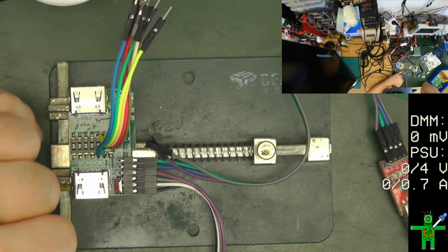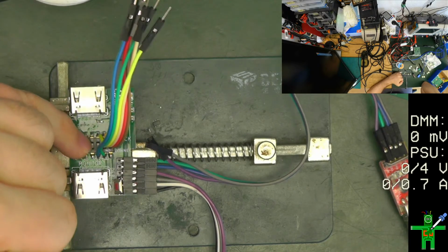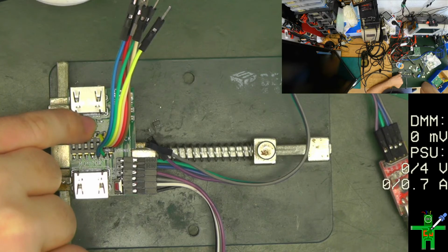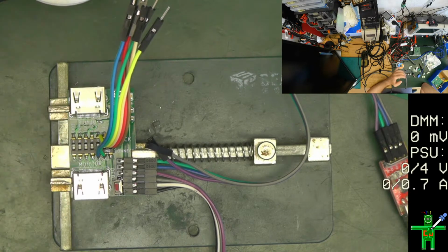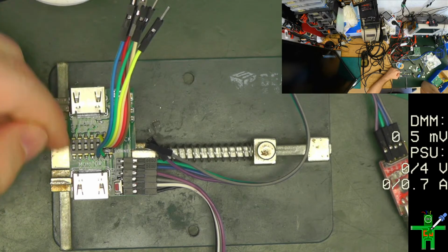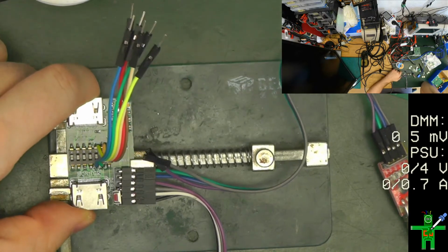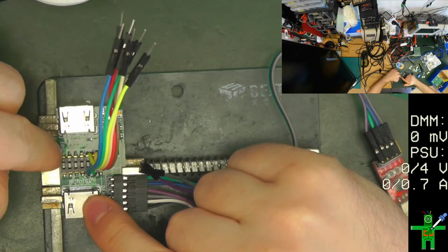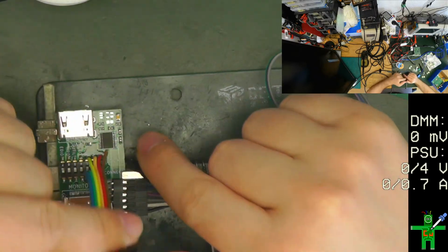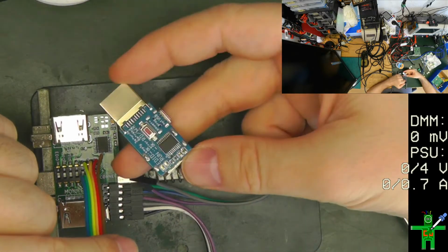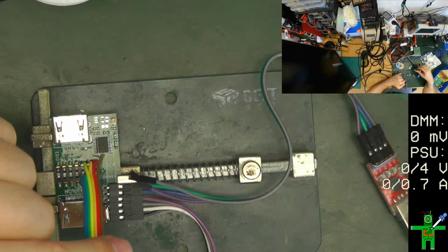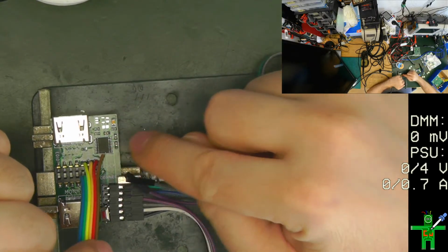If you want to have HDCP, then you can enable the two I2C lines. So DDC interface, which is two I2C lines, SCL and SDA, you can enable them, and then you have HDCP again. But you still disable the other interfaces, so it's up to you. This is the second improvement, and the last improvement is that now the programmer, which used to be separate, this one was the programmer for the EDID information, is now included on the board.